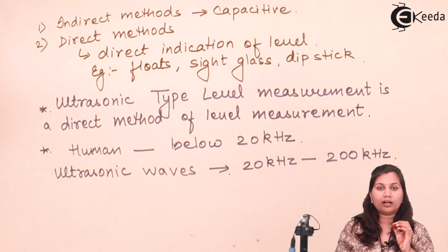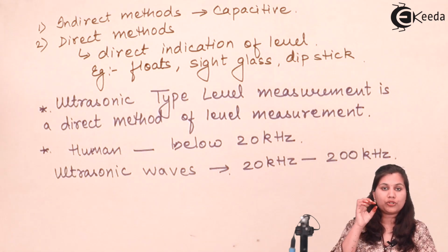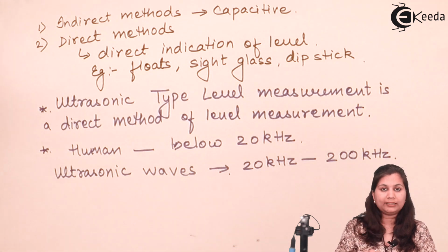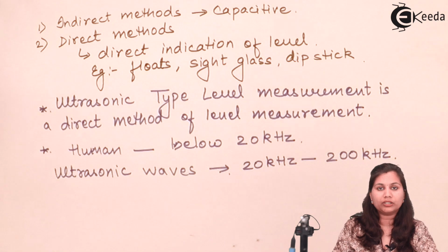There also, ultrasonic waves are generated. These waves strike the level of the liquid and return back, and the time taken by the waves to strike that object and return back is calculated to find out the level of the liquid.